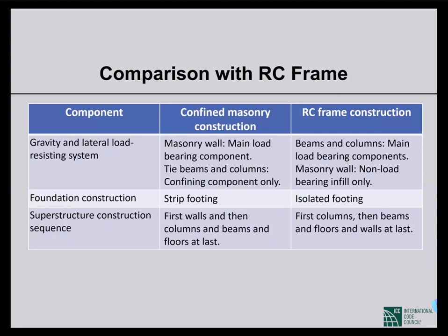So what is the purpose? It has been found in many past earthquakes that this type of construction of confined masonry performs much better than unreinforced masonry.